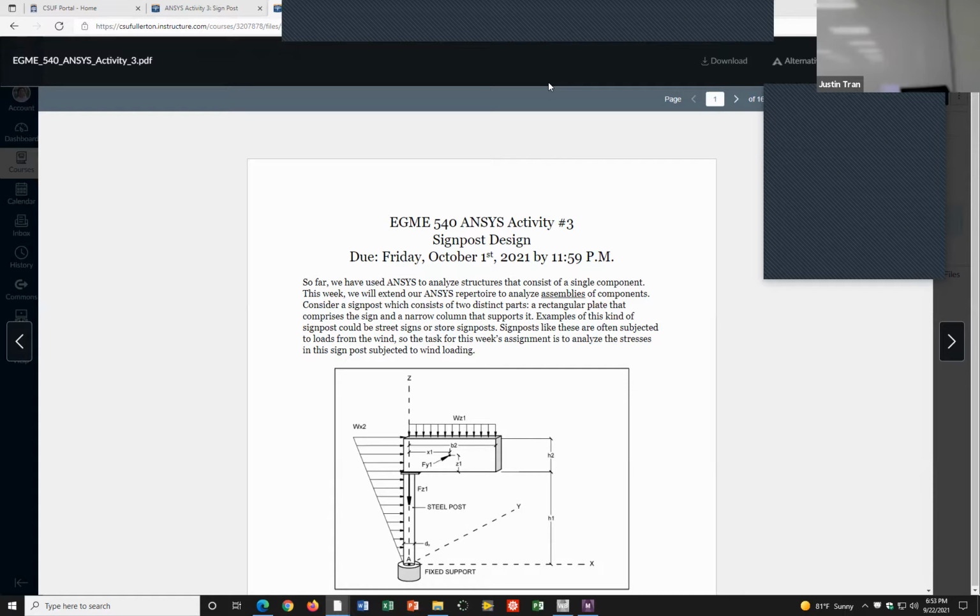Yeah, we can try forcing the mesh. We can try forcing the mesh on the post and see. Right now you have a pretty tiny element size. Usually you should, but I can see an issue where it might concentrate. Go to your mesh. Well, let's suppress the reflector. Let's just do it based on the side.